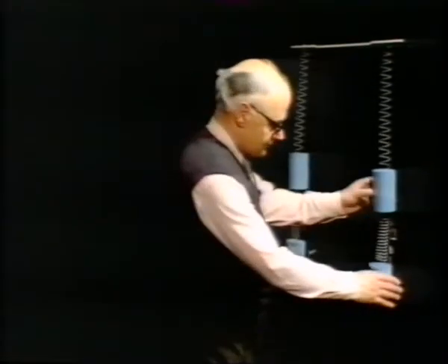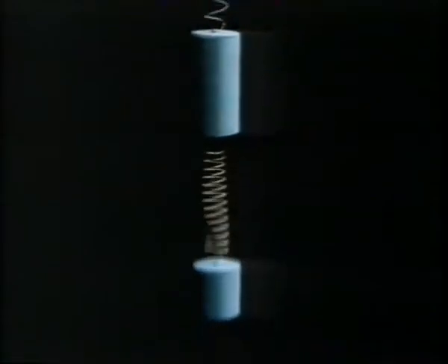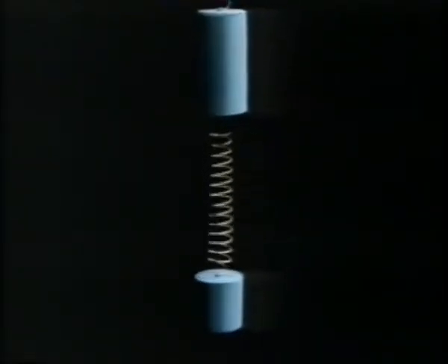Now, will I get sinusoidal motion for all free vibrations of this system? Well, the answer is clearly no. But even when the vibration is non-sinusoidal, the normal modes are still important, because it's a property of the normal modes that any free motion of the system is a linear combination of the normal modes.